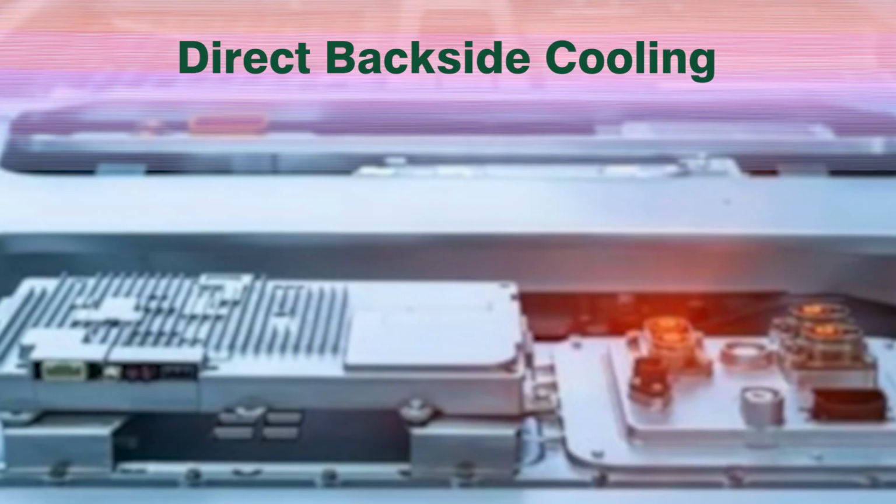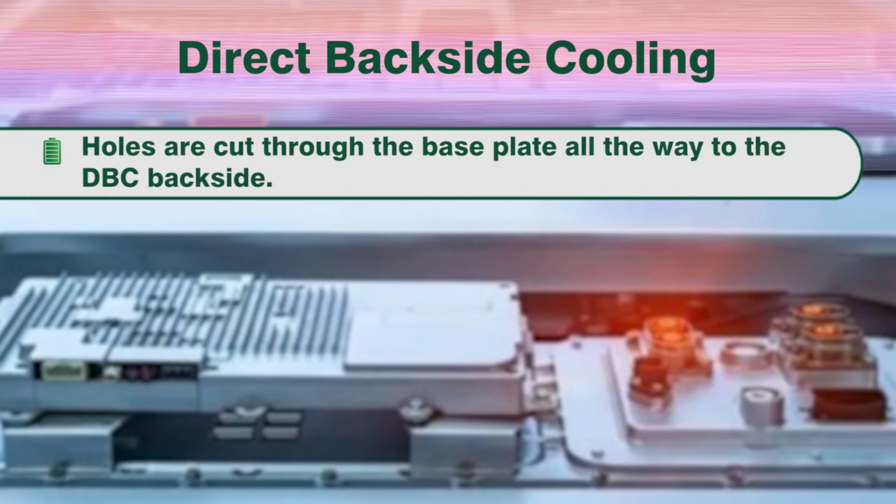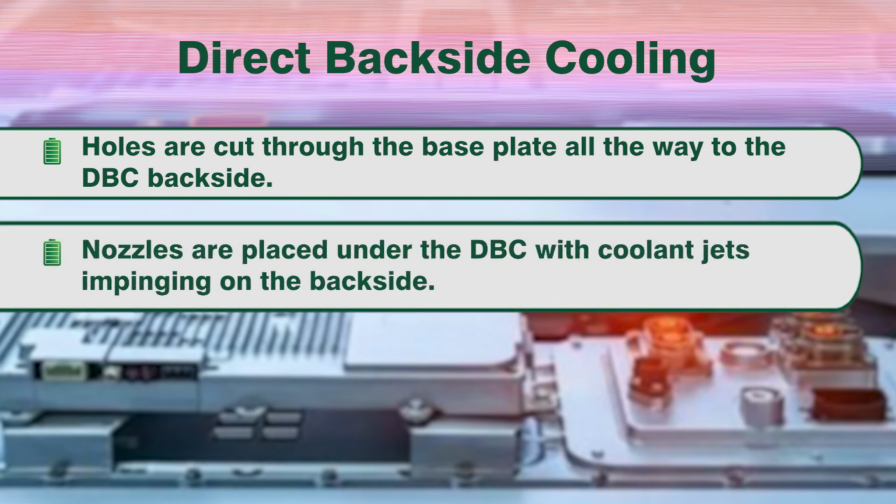The next one is direct backside cooling. In direct backside cooling, holes are cut through the base plate all the way to the DBC backside. Nozzles are placed under the DBC with coolant jets impinging on the backside. The nozzles are positioned in such a fashion that the jets are directly under the IGBTs and diodes.